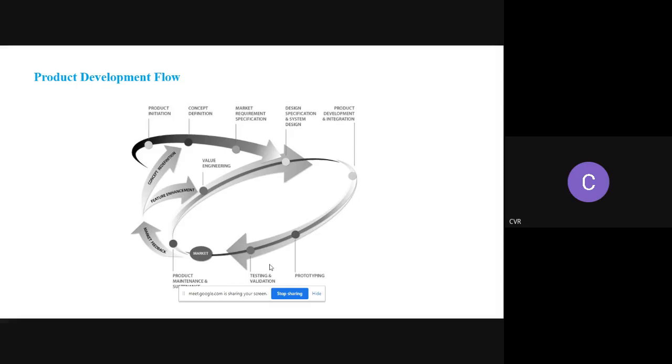Another thing is that safety testing and environmental testing are also important here. Safety testing is important because, assume in the TV some short circuit happens, there should not be any fire, or the TV should not burst. For that, they do a lot of testing, including a lot of short circuit testing. Ideally, what should happen is that your fuse should immediately blow. There are two types of fuse. One is your normal electric fuse. There, if a short circuit happens, the current will be more, so the fuse will blow.